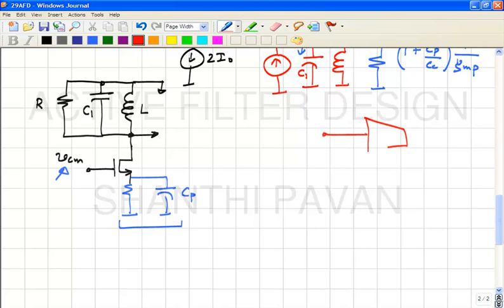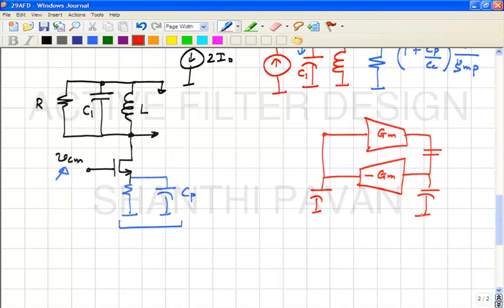So, this is the schematic of a gyrator, single-ended equivalent schematic, correct. What kind of feedback is there for differential signals? I mean, this is clearly a feedback loop, right. So, if I break the loop and go around it, what is the sign of the feedback? If I break this here, yank this up, what happens to this voltage?